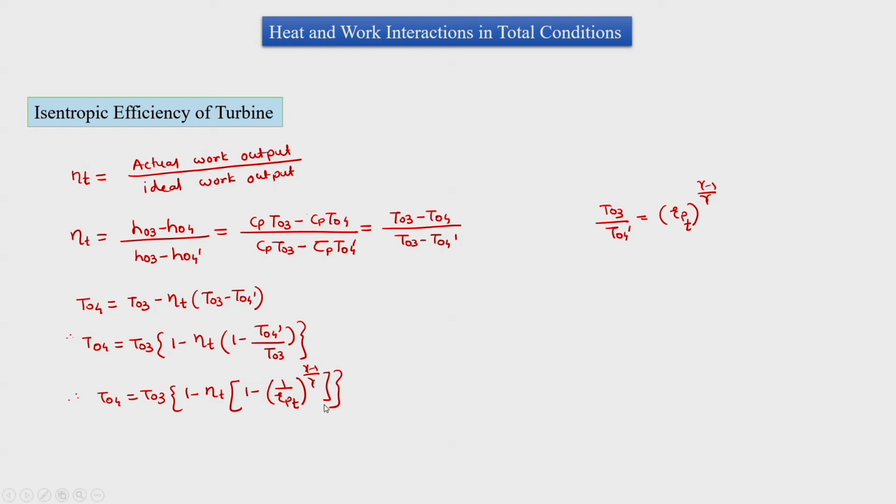Here it should be noted that we have used not Rp but Rp into T, the turbine pressure ratio. So there are two pressure ratios: one is RPC, the compressor pressure ratio, and the other is RPT, the turbine pressure ratio, and for the cycle we will generally be using RPC.